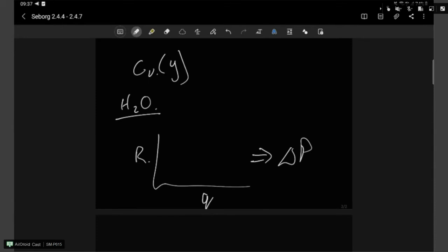So that CV, if you determine it, let's say for canola oil, you're going to get different values for CV when you relate that to the same experiment done with water or mercury, because those things act upon that valve in a different manner. There are different adhesion forces against the wall body and after the valve body, the valve stem, those sort of things. So it is not 100% constant. However, it doesn't change a hell of a lot.